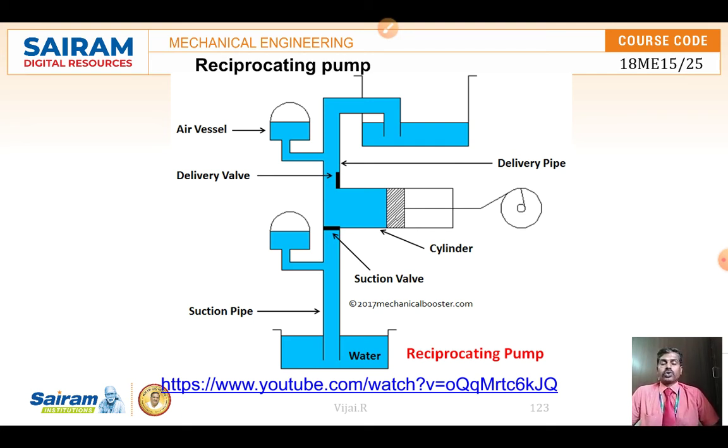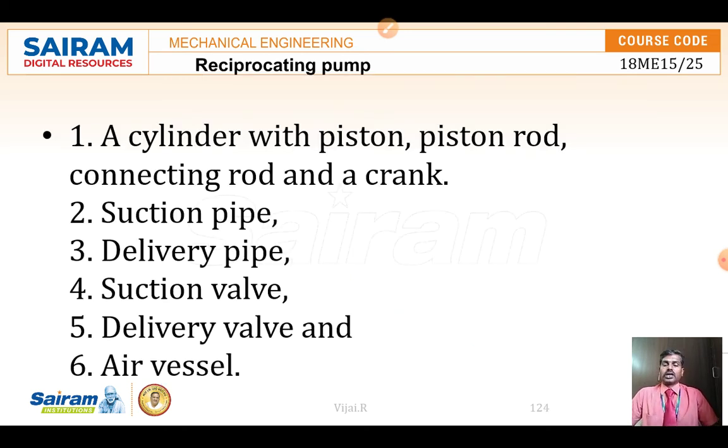When the electrical motor is started and rotates, the crank which is connected with the motor pushes and pulls the piston. The to and fro motion of the piston is caused with the help of the rotation, and inside the cylinder a vacuum is getting created. When the motor rotates half of this, it will create the suction, and the water is getting sucked inside.